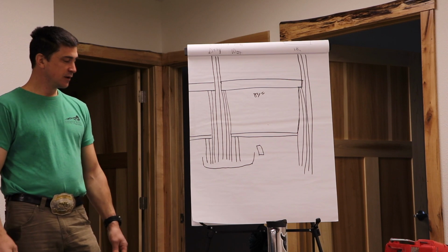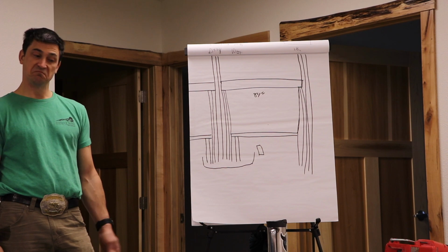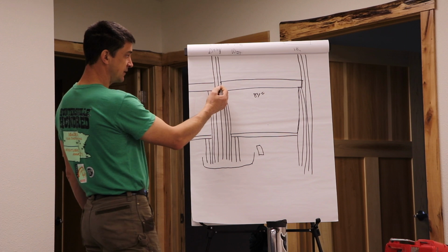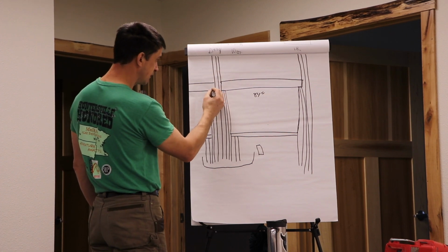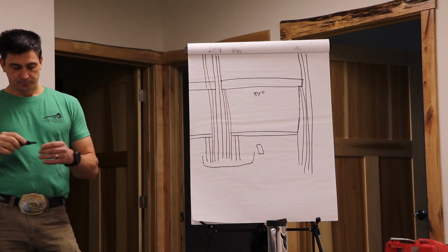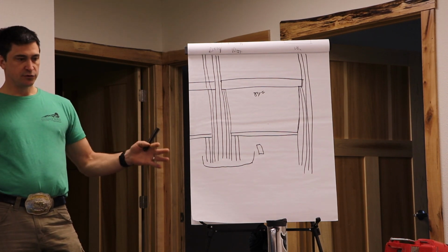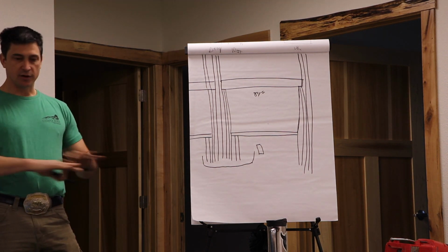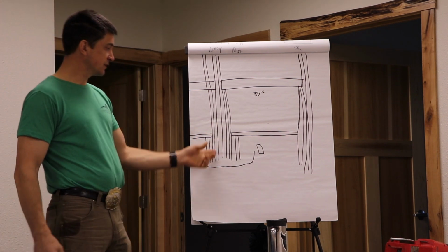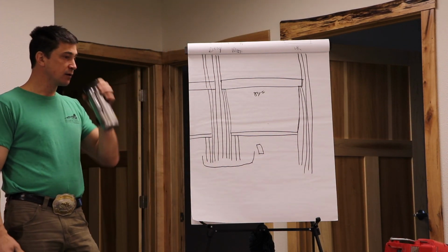Did you need to have 10 pieces of framing slammed together there to support that structurally? No. Okay? The other one is like, if the engineer says we need 2 king studs here, well then we obviously need 2 king studs there. That's somebody that got stuck in the I'm doing framing box, and he didn't think about anybody else on that project. And he didn't think about the customer because he just put $100 of material there right at the window when 50 would have been fine.